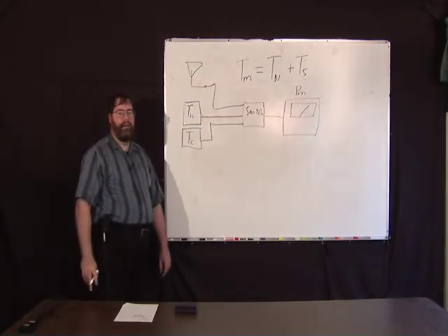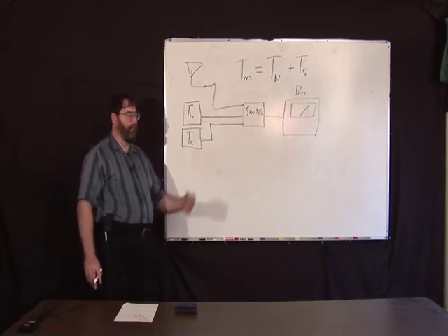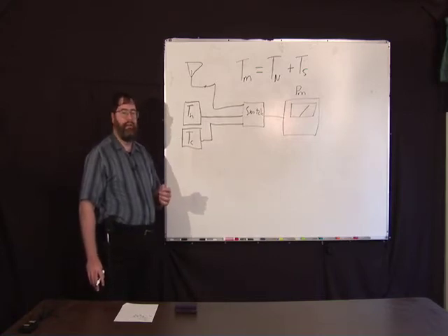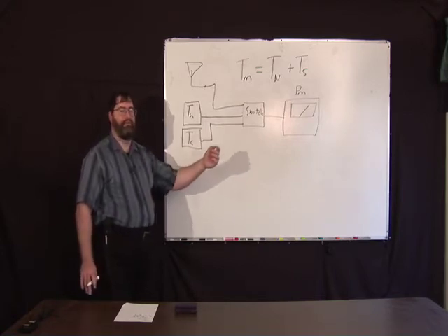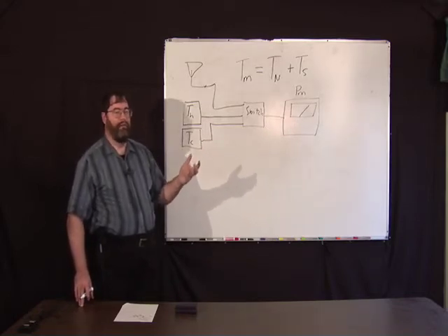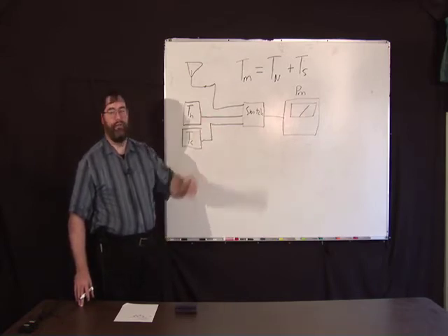If we have a high enough gain antenna, and if you watched last week, you know that a high gain antenna means in a particular direction, there's a lot more power radiated or received than would be for an isotropic radiator, which means it doesn't receive much from other places. So high gain means that you have a small angular extent that the antenna is looking at.